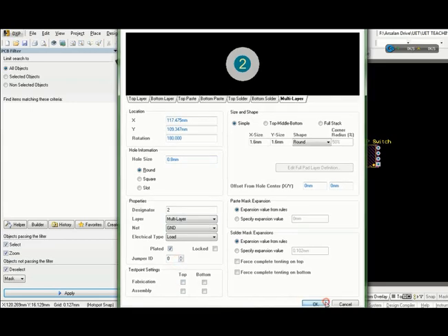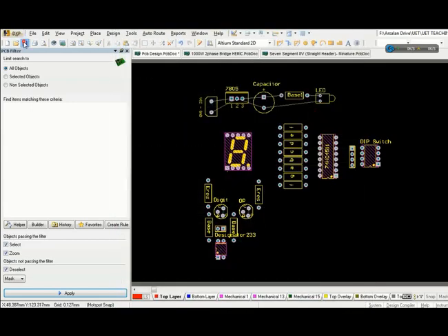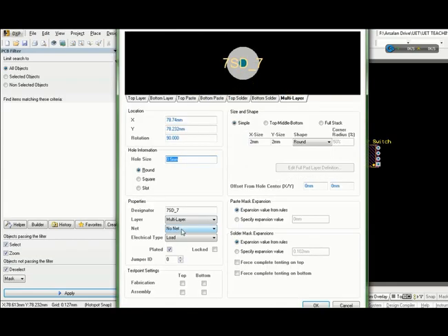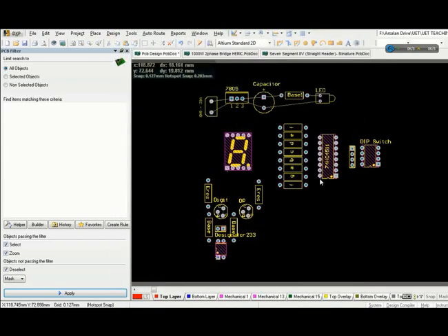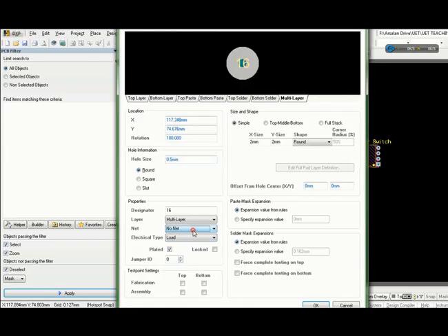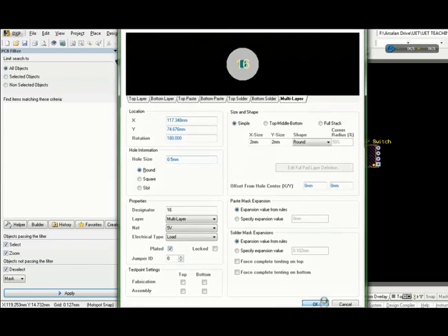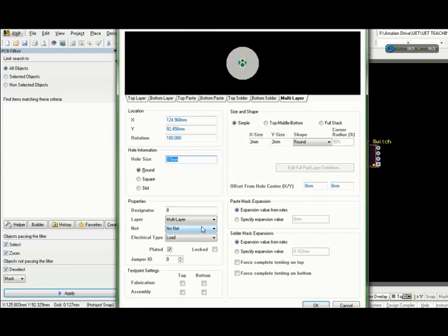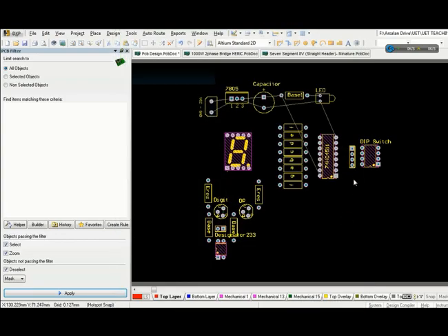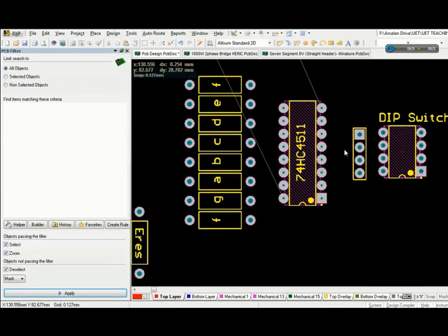And this way, I guess this is the 7 segment over here, the common cathode, and in this way you can have that common cathode point, and that can be connected to your resistor or whatever 5 volt. This is the 5 volt pin, and here I'm showing you the DIP also, the 74HC4511.